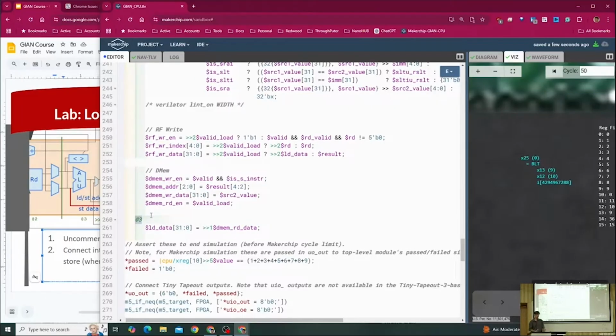And the functionality here, if we just simplify this, glom everything into 1 cycle, imagine the load happens instantaneously within the cycle. Everything is in that 1 cycle. We're not looking ahead, we're not looking behind. So the fact that we had to move this to stage 4 is just a fact that we laid out the pipeline differently. We want the same functionality. So that's kind of a key. If I want the same functionality, then I should only be changing the ats.